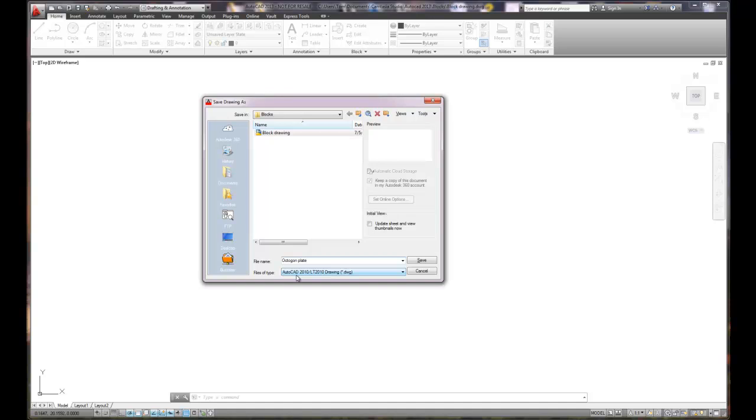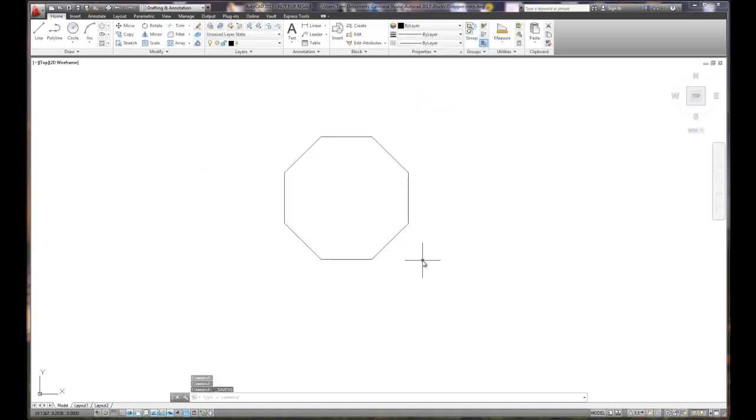We're going to save it as an AutoCAD 2010 drawing. When you're saving work, if you need to save in an earlier version, for example because you need to strip some of the new features for lasering or other aspects, you can save it under earlier versions. If I'm going to do something that may or may not have compatibility issues, I'll always kick it back to Release 14 or AutoCAD 2000. But in our case, AutoCAD 2010 is perfect. We'll hit Save.